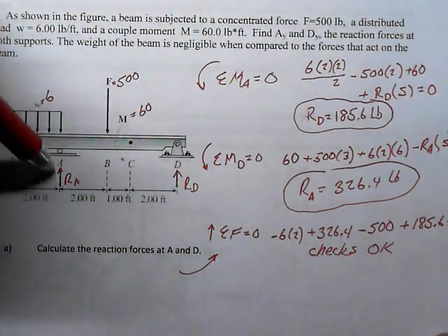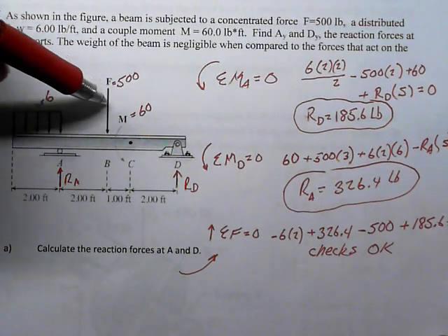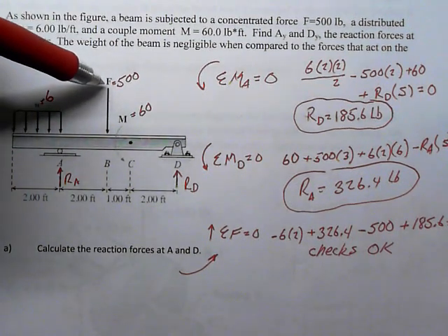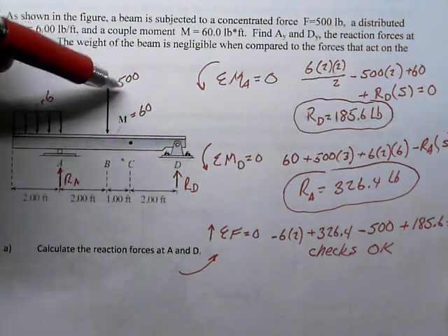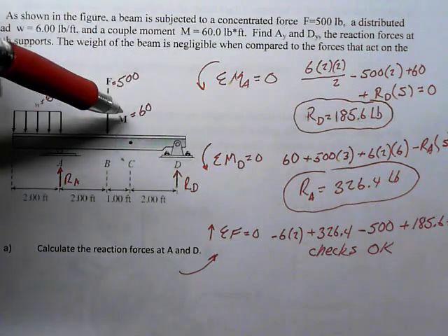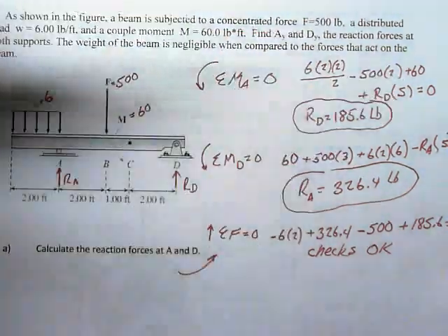Then the other moment, let's see, R_A causes no moment about point A. And I called moments that are counterclockwise positive. And so the moment due to F, which is the 500 times 2, is going to be a negative moment. My moment, which right here is 60, will be a positive 60 moment.